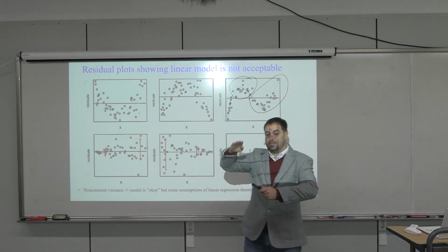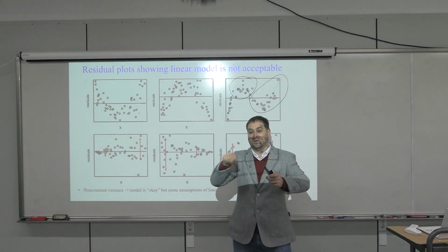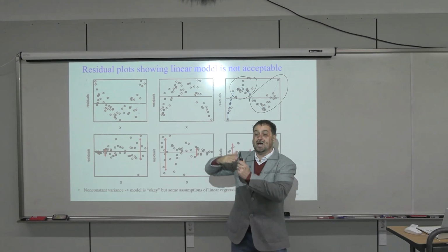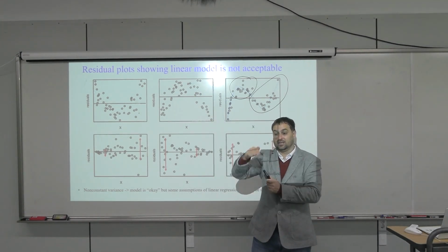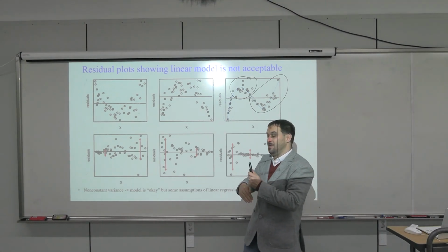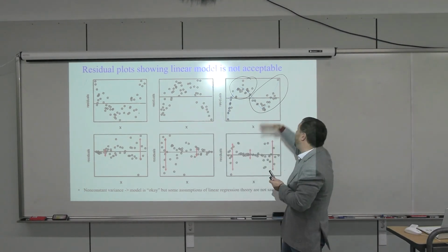And also, in the same measuring device, the bias might be a function of the weight. So maybe at the low end of the measuring range for that device, there's a negative bias, and then maybe there's a positive bias at the higher range.